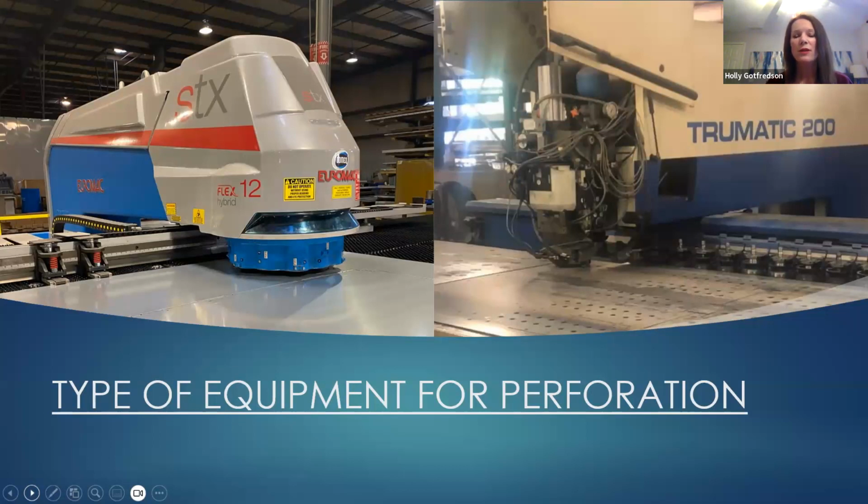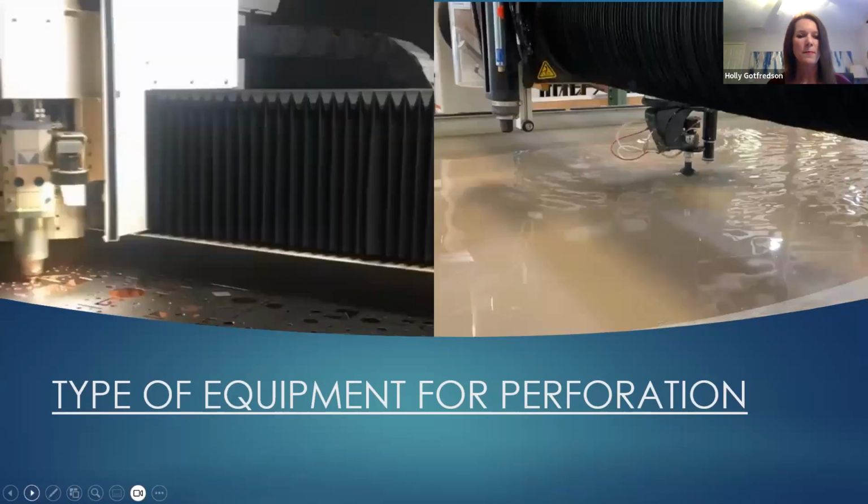Typically you can buy tooling for these machines to achieve multiple different types of patterns. Those are going to be standard hole sizes. You can also do rectangles and ovals with those. You can also put a gang punch in those so that you can hit a panel once but create multiple perforations. So this is a good economical way to achieve a perforated product.